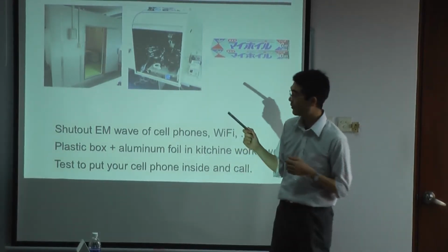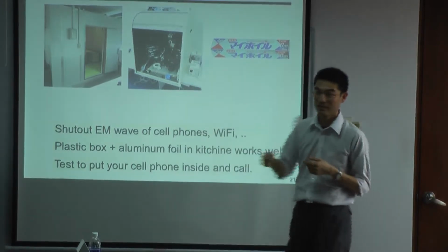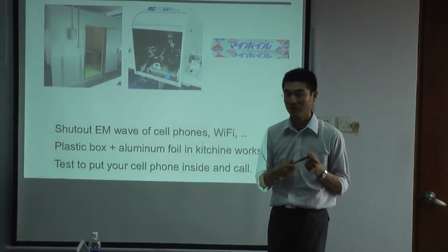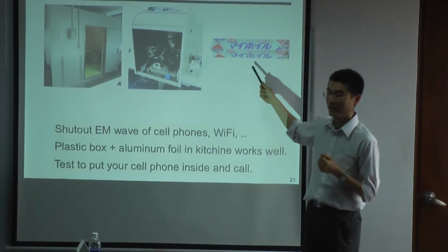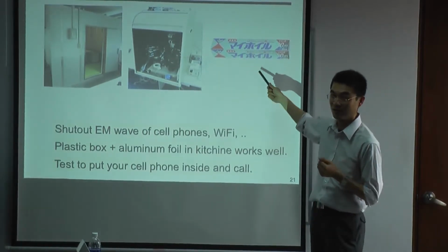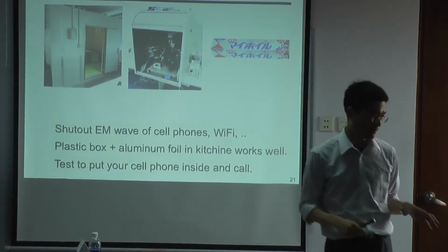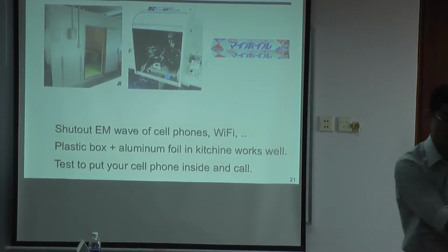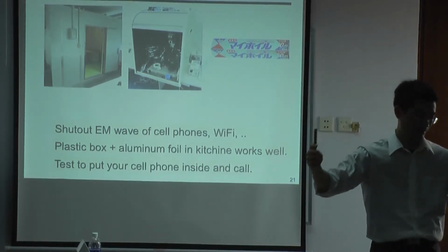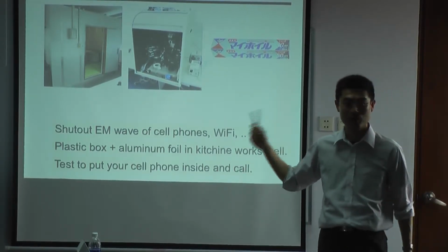And actually, this shielding does not work well. And I tried something, and this is aluminum foil. You can buy this in the supermarket, just $1. Put the aluminum foil on, for example, this kind of box. Shield the box with this aluminum foil. It actually works fine.